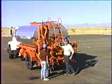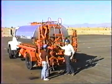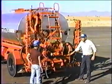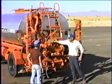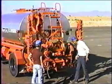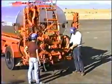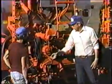Okay, I'm going to go over a few things on the back end here that are purely mechanical, things that you should know about. First of all is the binder on the bar that we just used. When we loosen it up like that and it won't come off, the bar is dropped down just a little bit. Pick it up with the hydraulics, and now we can get that loose. Always hook them up on the hangers that are here. If you don't do that, when the bar goes down and then comes back up, this runs into some of that expensive mechanism on the top and usually breaks something, and then you've got a leak or a valve that doesn't work.